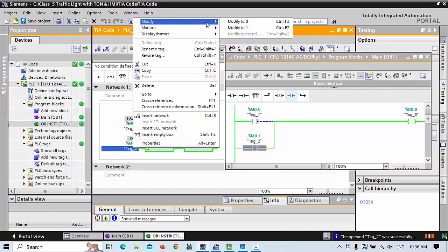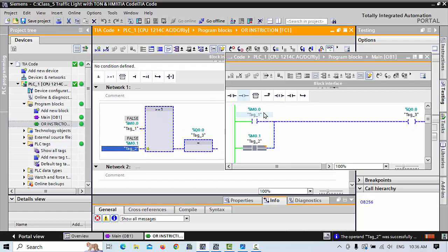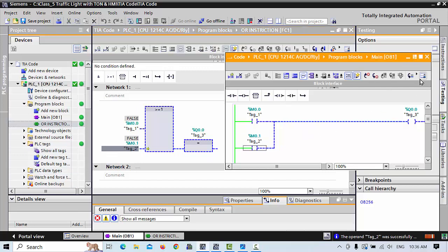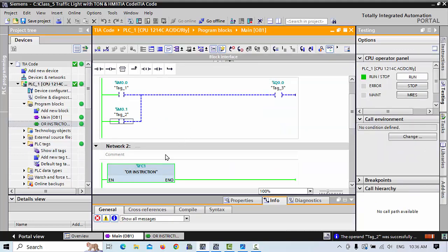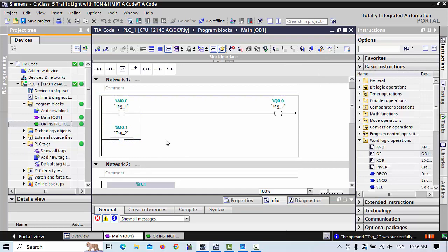When you stop this execution, this will stop. If this one is on or this one is on, you can also put any input address from the field, I0.0, I0.1 or I0.2. Any signal you give in our instruction, your output will be energized. Same if you like to increase this one, stop the execution. For example, stop the simulation, and here we can add one more.